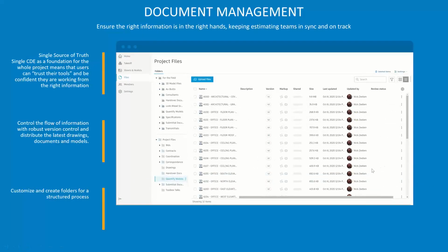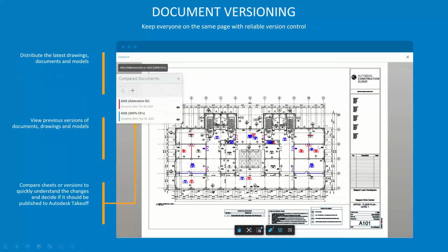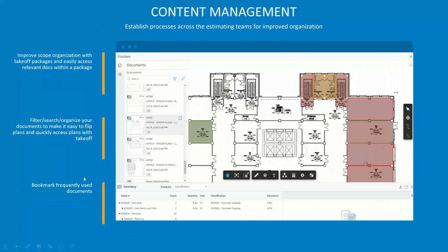And then obviously we still have all of the permission controls, comparing documents. So a lot of these slides are just repeat. This one here is a live look at what the Takeoff module looks like. When we open up a document or a specific view within Autodesk Docs, we can start to create quantities and quantify different areas. So just using tools, you're basically creating regions, selecting model elements, whether it's a 2D view or a 3D view, and assigning different classification groups to those parts.